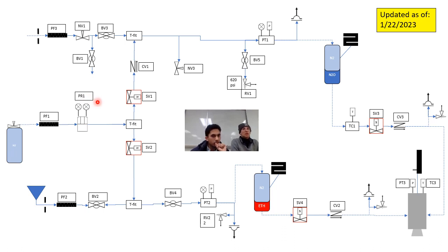We do not want it to turn into a gas. And so we're going to pre-fill this with nitrogen, and then eventually, and we'll get to this later, we put the nitrous oxide in and open these valves and start letting it flow. Instead of the nitrous oxide coming out as a gas and expanding and filling the space, it's already going to be pressurized, so it's just going to come out as liquid.